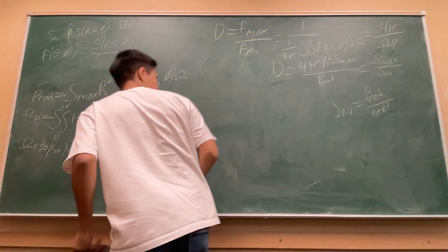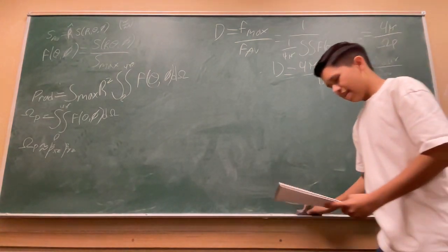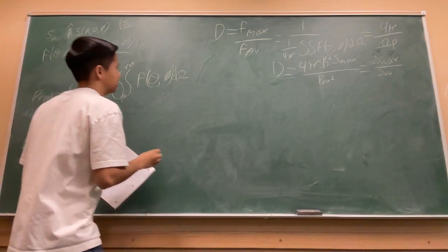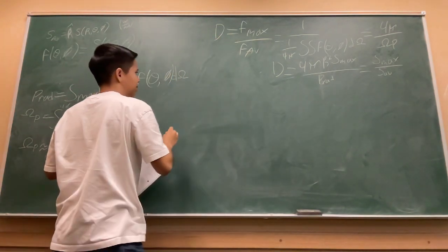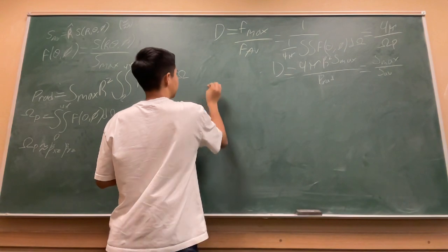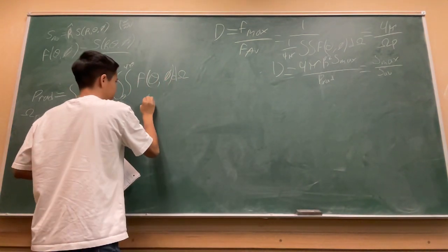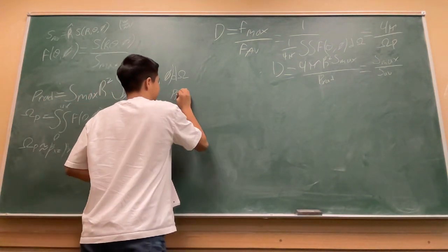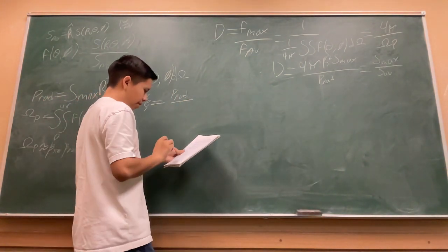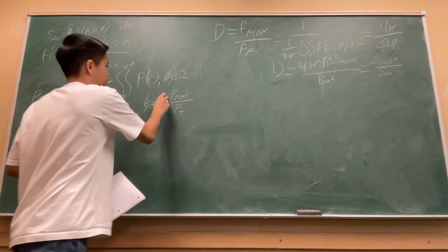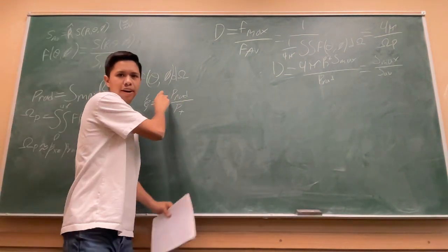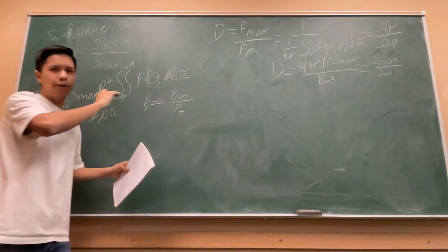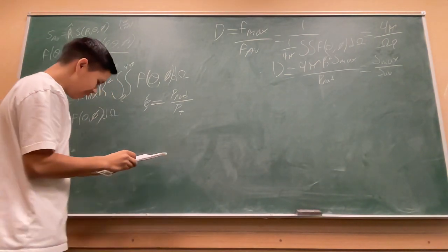Okay, now, moving on, we're going to look at the gain of an antenna. So the gain accounts for ohmic losses in an antenna. So it's related to the directivity, but before we start, we're going to look at the radiation efficiency, which is given by this Greek letter. That's going to be equal to the power radiated over the transmitter power. Okay, so the power coming out of our antenna versus the power that we put into our antenna. So this is kind of taking into account the power lost in our antenna, in a way.